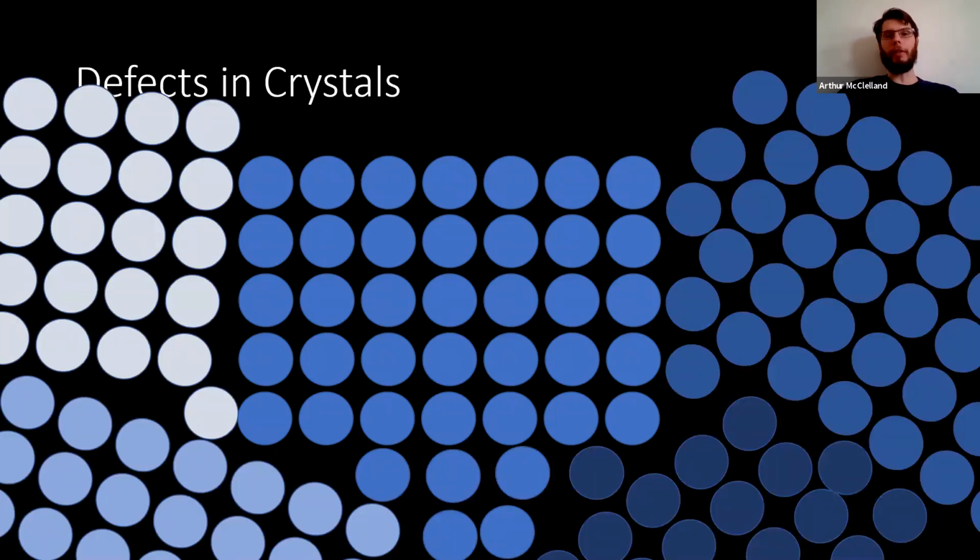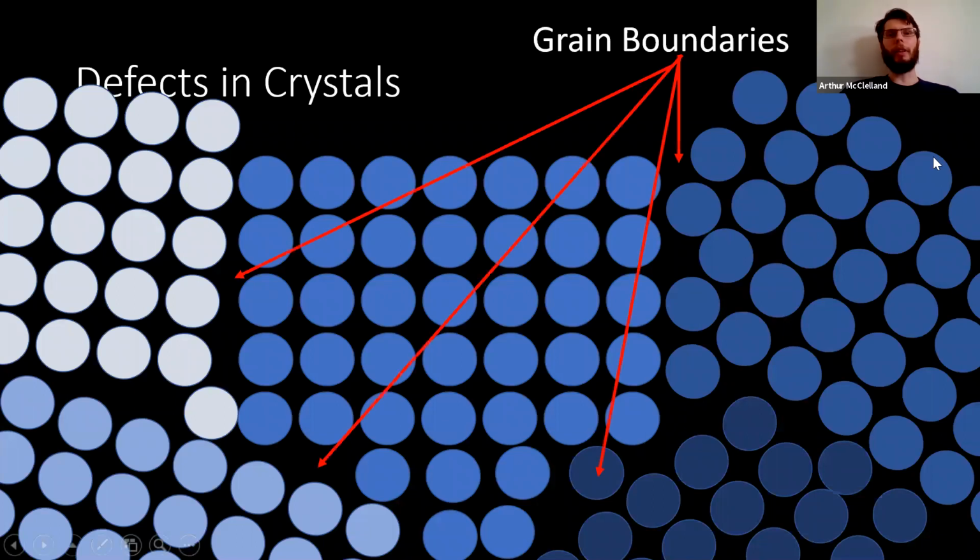Often materials are polycrystalline. So here we have a bunch of crystals, and they're all oriented a little bit randomly to each other. And so then we have what material scientists refer to as the different crystals as grains. So at the grain boundaries, at the interface between the different crystallites, we get lots of defects. So certainly lots of effort goes into growing single crystal material.